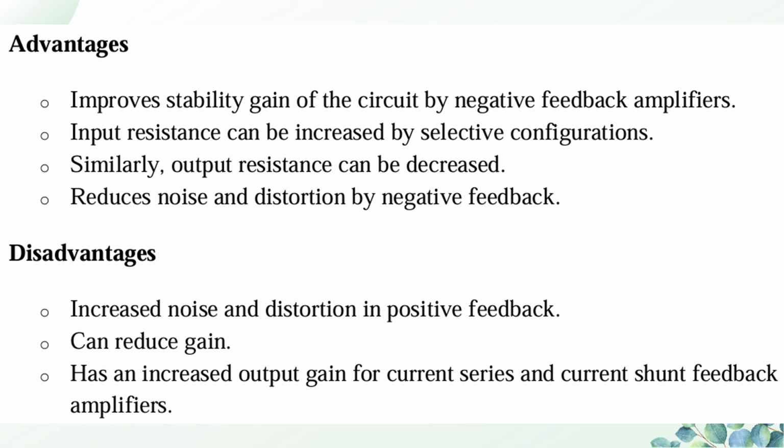The input resistance can be increased by selecting the proper configuration. Always, for better performance of the amplifier, its input resistance should be larger and its output resistance should be smaller. The next advantage is that it reduces noise and distortion by using negative feedback.